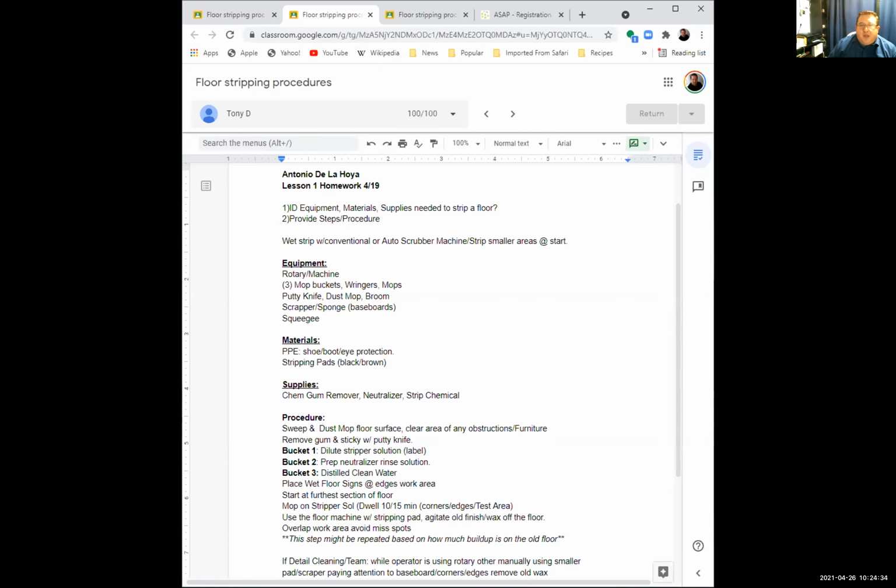Yep. And another good point along the lines of this is I'm also going to stagger my coats in the form of the coats up next to the edge. So if my first coat is along the edge, my second coat, I'm going to keep out away from that edge a little bit. And it depends on the area it's at. In a multi-purpose room, I may be as far out as a foot away from the base.